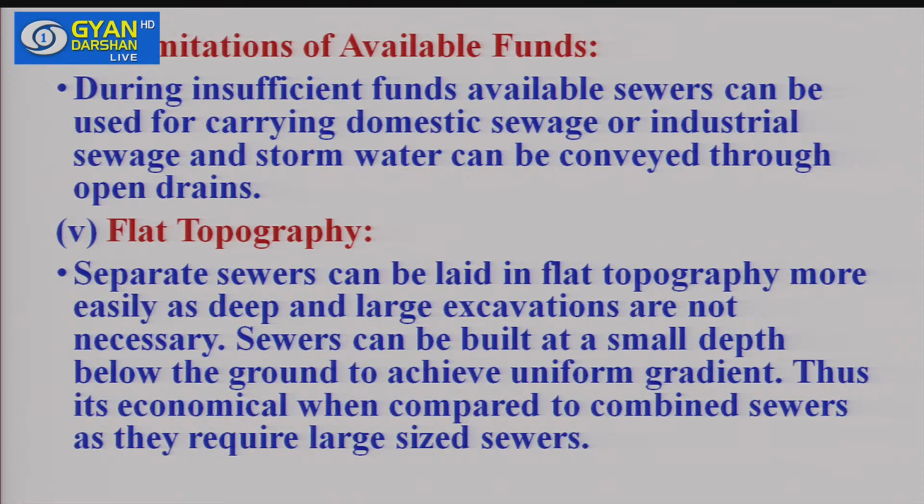Then flat topography. Another situation is flat topography. Separate sewers can be laid in a flat topography more easily, as deep and large excavations are not required. If it is an uneven topography, then we need large cutting and excavations, which will cost more.